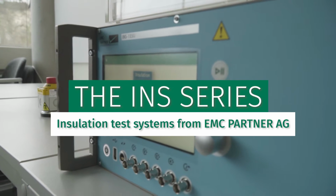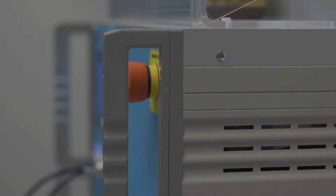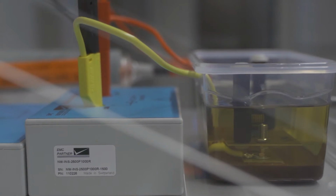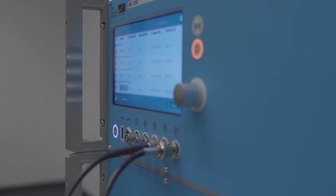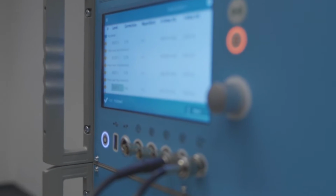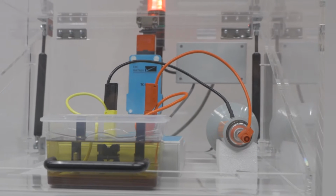Safety testing of electrical and electronic products is vital in all branches of industry. The standard impulse 1.2/50, also known as the lightning impulse, is used in electrotechnical applications such as household and industrial equipment. There are also specific tests for equipment mounted in the power distribution grid, such as electricity meters, protection, automation and control equipment.